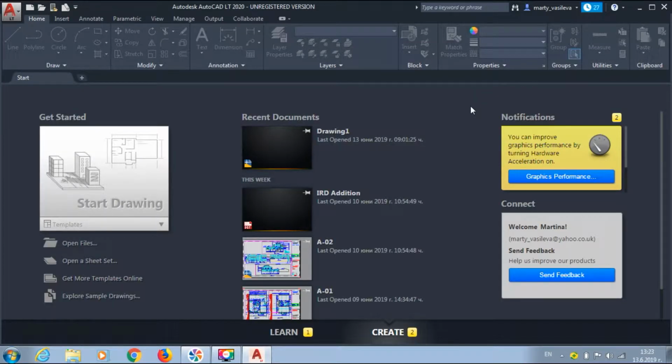In my first lesson I'll show you how to change your AutoCAD to the classic interface known as Classic Workspace. Just to explain to you, Classic Workspace organizes and displays commands and toolbars in one and the same way, so we can all use the same interface whatever version of CAD you have. I have 2020. Today I also will show you how to draw a single line, straight or at an angle, and how to save your drawing.